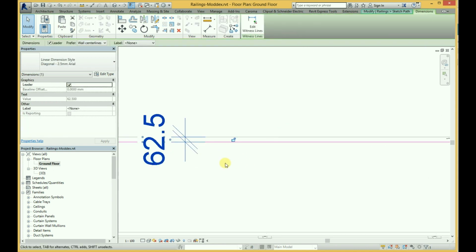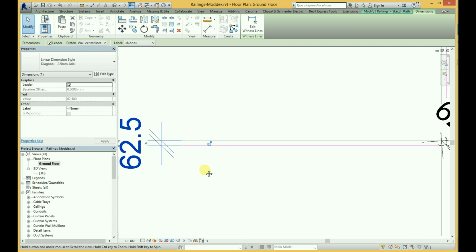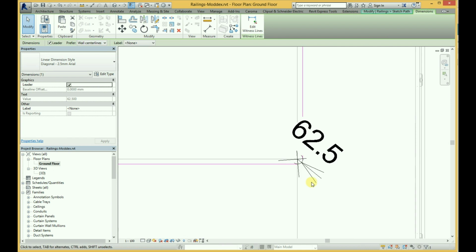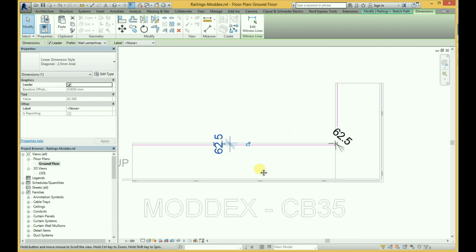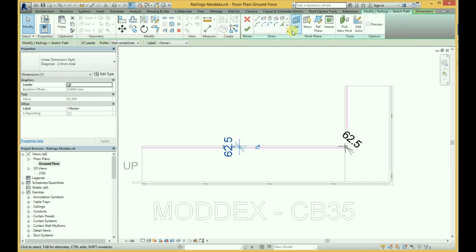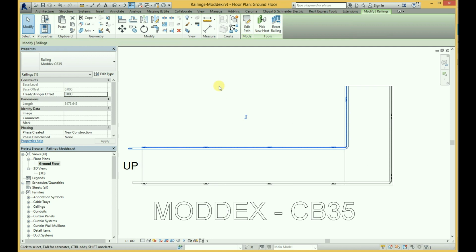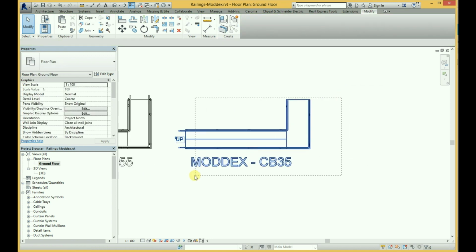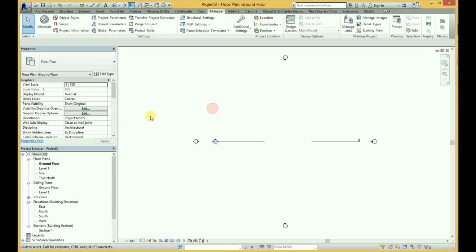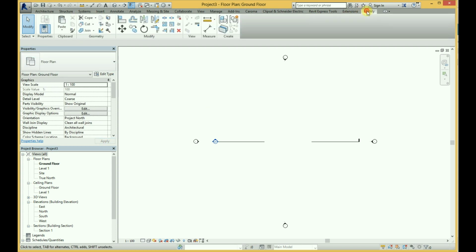The next thing is to edit the path, and then in there we can see I just take the dimensions of the offset from the edge of the ramp or floor and any radius bends that have been added in there. Once I have that information, it's then a fairly simple process of copying to the clipboard, going to the desired project and pasting that.